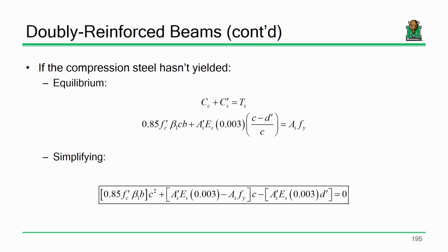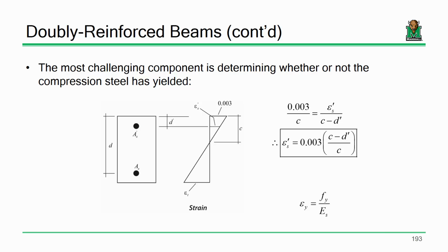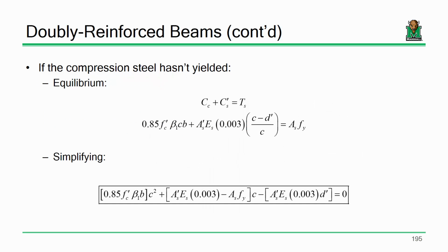in the bottom. So how do we get the tensile force of the steel in the bottom? Well, that's just AsFy. No matter what, I'm still assuming this is yielded, and that will almost always be the case. Well, actually, it has to be the case. That's because we have that strain limit of 0.004. It's trying to enforce that that tensile steel has to yield.